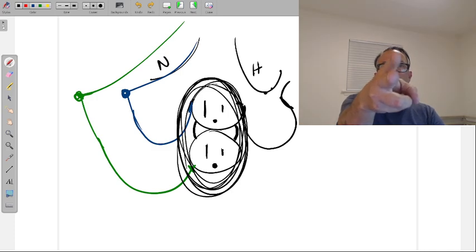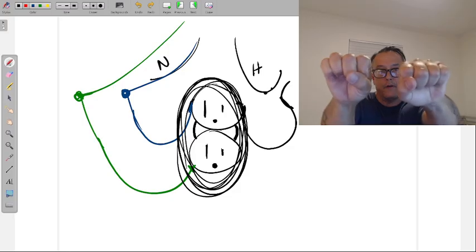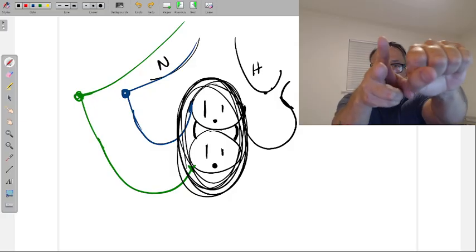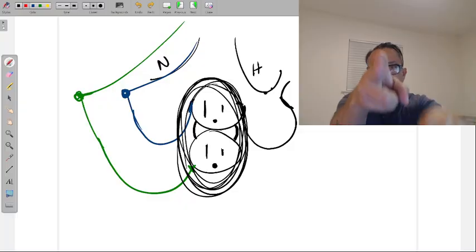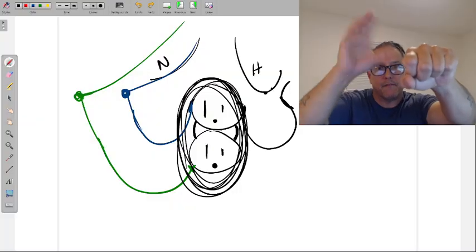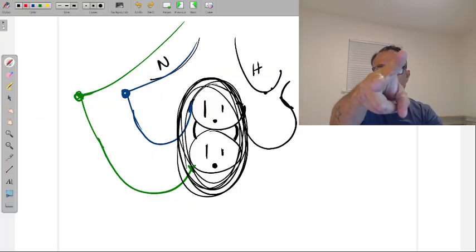Cut this way. You go around the wire, but here's the trick. Don't go up, down, cut. Open, go side to side, cut. And then you turn them. And this turn already separates the insulation. So again, you don't cut straight down, because if you cut straight down, now you're going to be on the copper and you're going to have to do the little spin thing. So you cut sideways and you just turn the wire strippers.